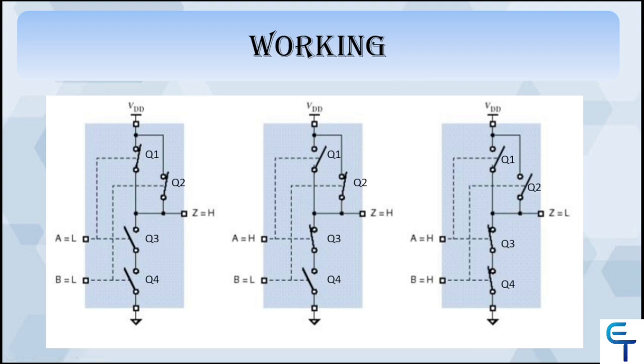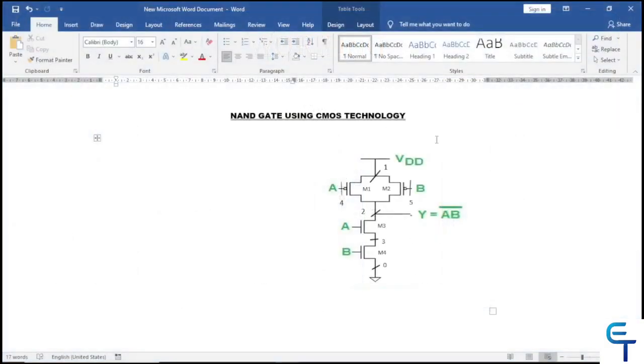Now let's write the ngSpice code and check the output. So this is the circuit diagram we will be referring. We are having a PMOS connected in parallel and NMOS connected in series. So let's write the code. First line will be the title line. So NAND gate. Now let's define VDD, which is connected between 1 and 0. And let's say the value of that is 3.3 volts.